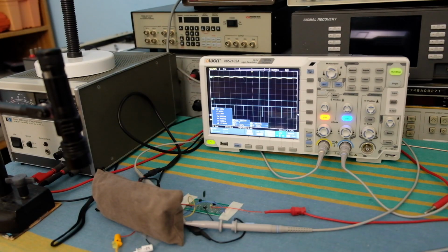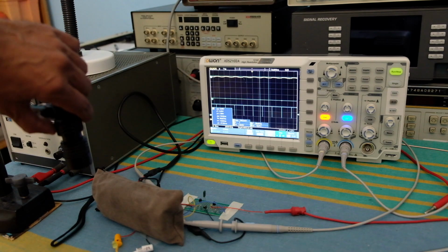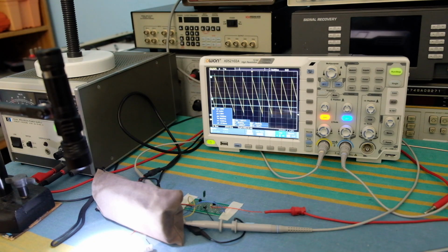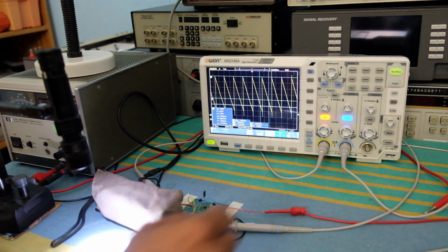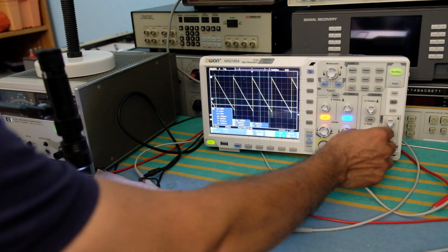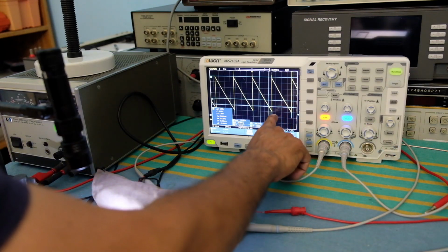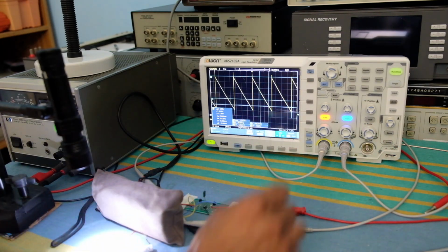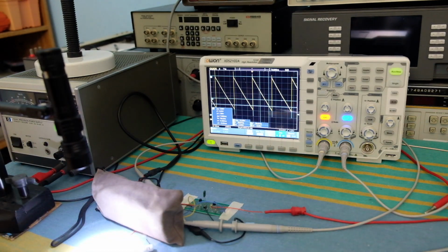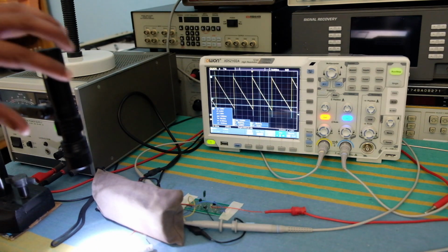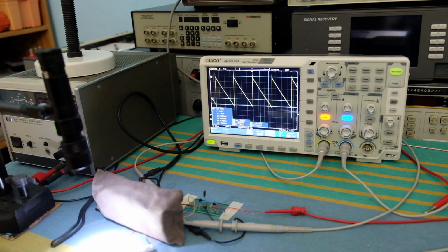So here's the yellow LED now with the 1 nanofarad capacitor, and as you can see, this one made it to about 1.5 volts or so, and again extremely linear over the range, a very nice performance. And if you measure the voltage down here and integrate that amount of charge, you can calculate the current provided by the LED based on the capacitor and the voltage change. So this is an excellent measurement that one can use to characterize this LED.